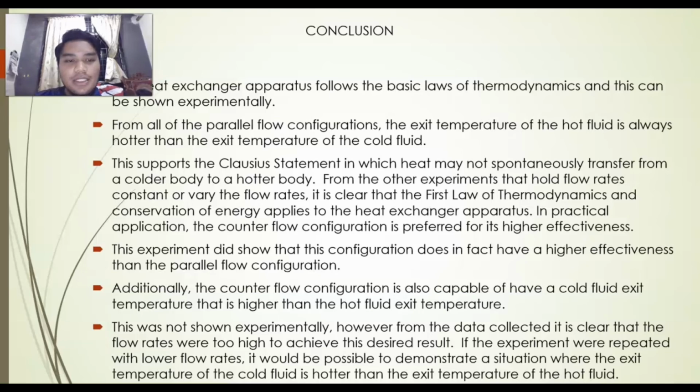In practical application, the counterflow configuration is preferred for its higher effectiveness. Additionally, the counterflow configuration is also capable of having a cold fluid exit temperature that is higher than the hot fluid exit temperature. This was not shown experimentally. However, from the data collected, it is clear that the flow rates were too high to achieve this desired result. If the experiment were repeated with lower flow rates, it would be possible to demonstrate a situation where the exit temperature of the cold fluid is hotter than the exit temperature of the hot fluid.